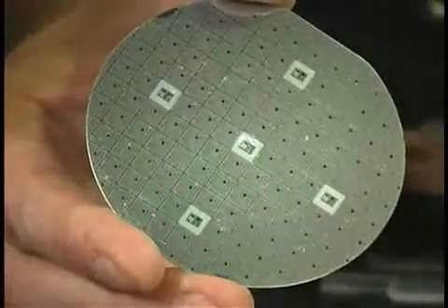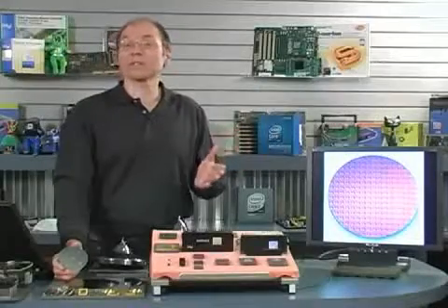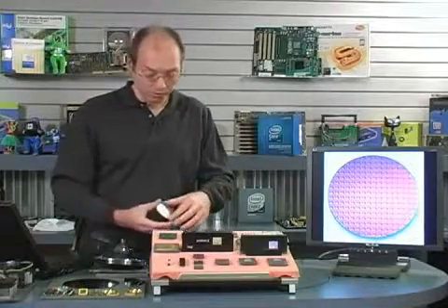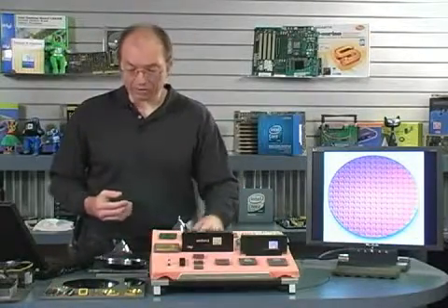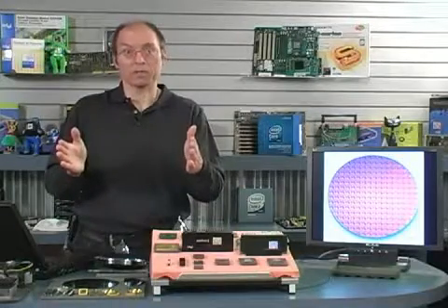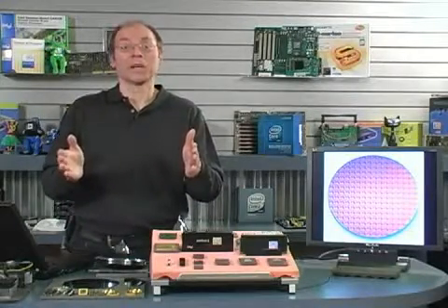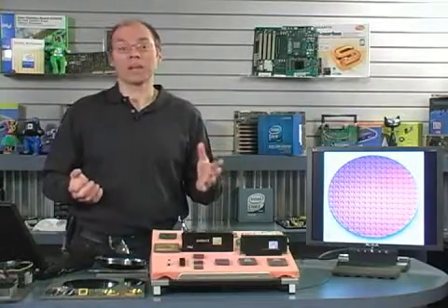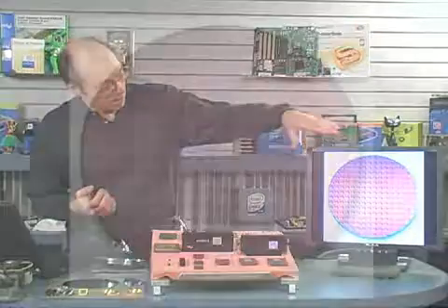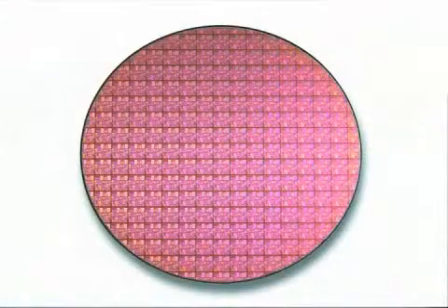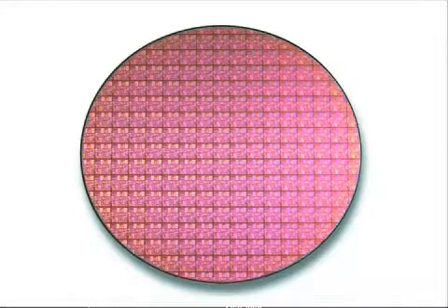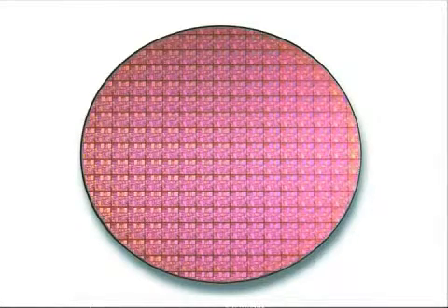Now, wafer sizes have increased over the years. Most recently, we had a transition from 8-inch wafers to 12-inch wafers. And what that means is that the wafers being used for most chips today are 12 inches in diameter. Now, as the wafer size increases, the number of chips that can be imprinted on them goes up. For example, this wafer image that I have here was actually originally an 8-inch wafer. And with the 8-inch design, 177 separate chips could be etched onto this wafer.